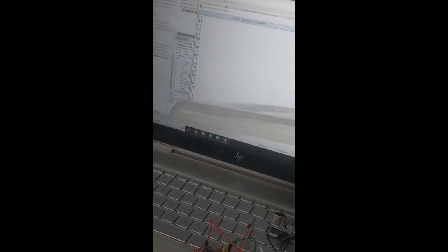So as we get the object closer, see right now we're at 11 centimeters, 10. As we bring it back up, we get an increase in centimeters. So I'm going to bring it way up here, way down here. It's pretty responsive. Surprisingly not that noisy. But then again, the resolution isn't that high because I have not enabled decimal values in the UART, but